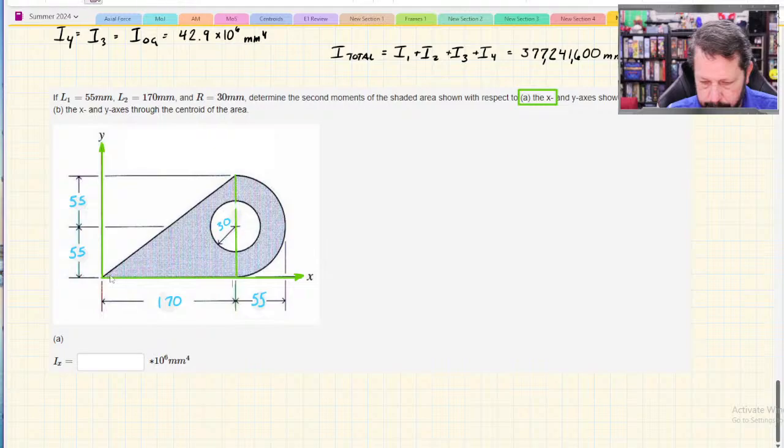You know, there's actually nothing in there. So I'm going to have a triangle, a half circle, and then I'm going to have one negative shape, a circle in the middle that's cut out. So each one is going to create its own moment of inertia about the x-axis. And then we're going to give the cutout circle a negative moment of inertia to account for the fact that it's not there. It's missing. So part 1 is going to be our triangle. Part 2 is our half circle. And part 3 is our punched out hole in the middle.